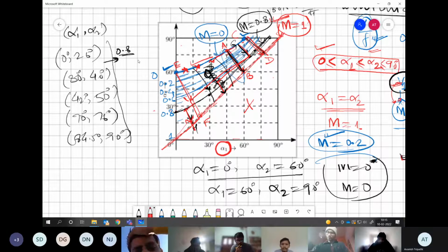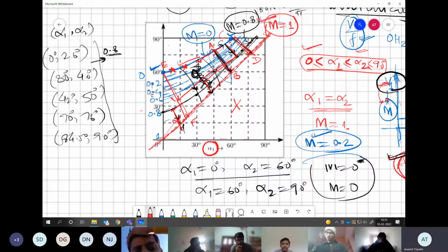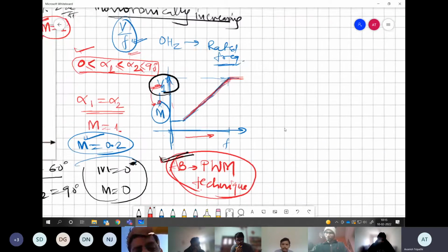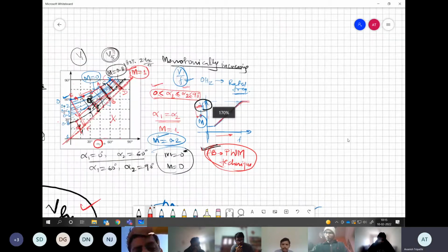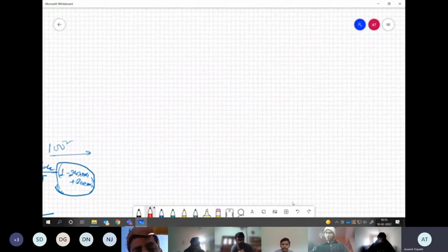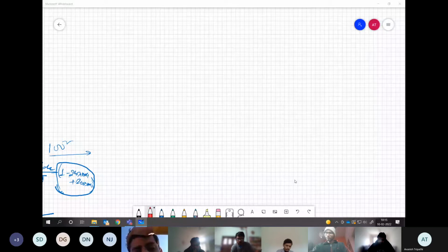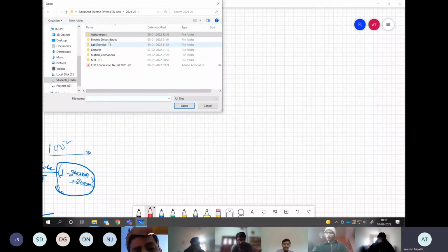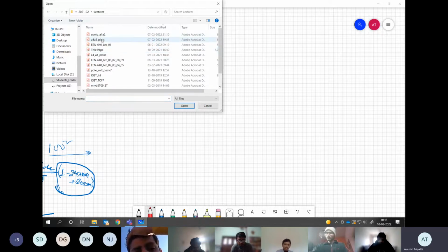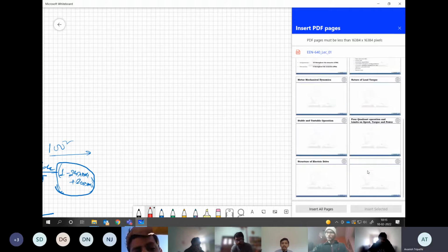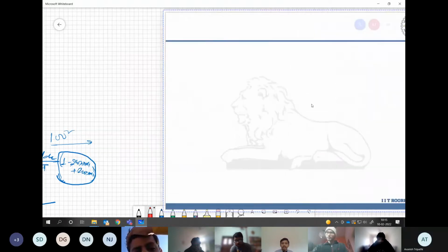The easiest thing could be to try to eliminate the most dominant harmonic in the system. When we talk about the three-phase system, which are the harmonics present? The fifth, seventh. That's all. Dominant.